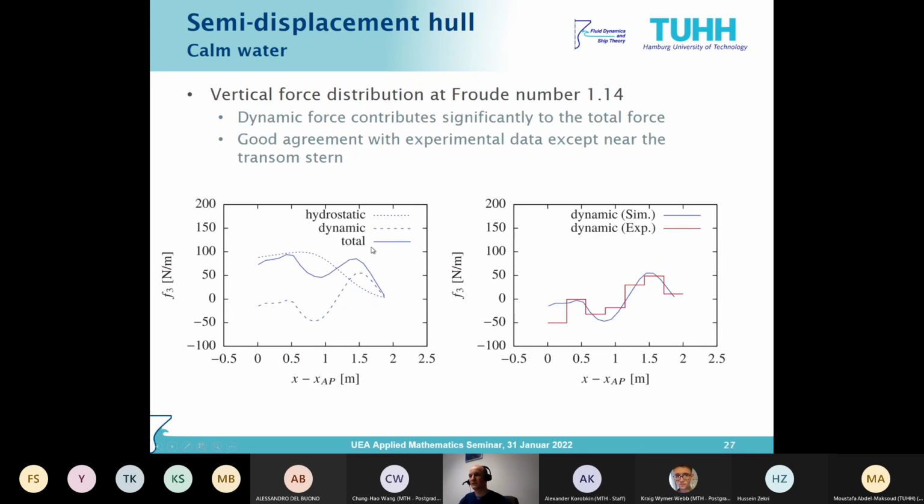And here you can see a comparison of, first of all, the vertical force divided into its hydrostatic part and dynamic part. You can see it's a semi-displacement hull, so both pressure parts play a role, but the dynamic part also plays a significant role, especially at the bow.